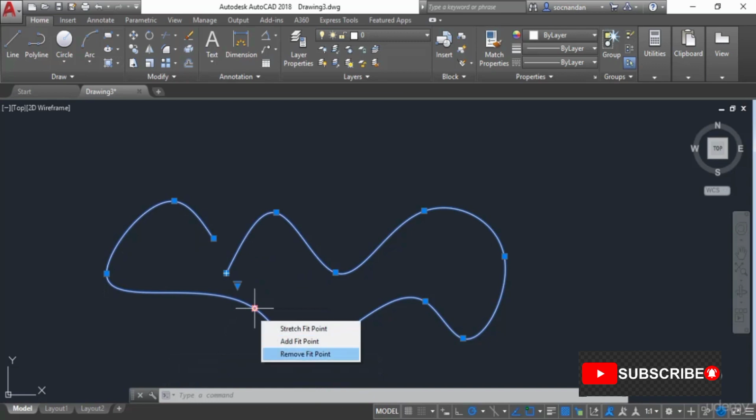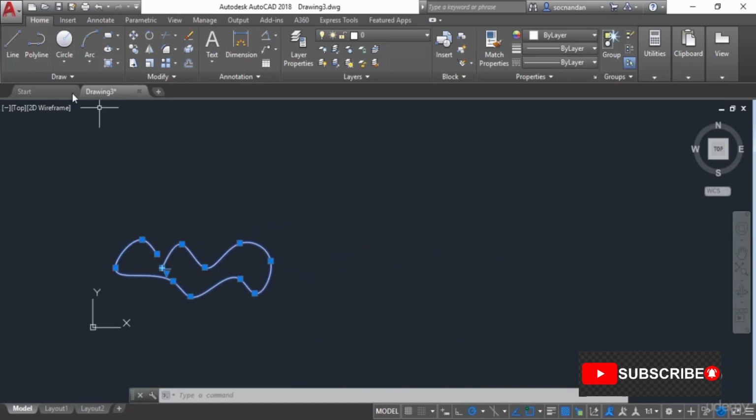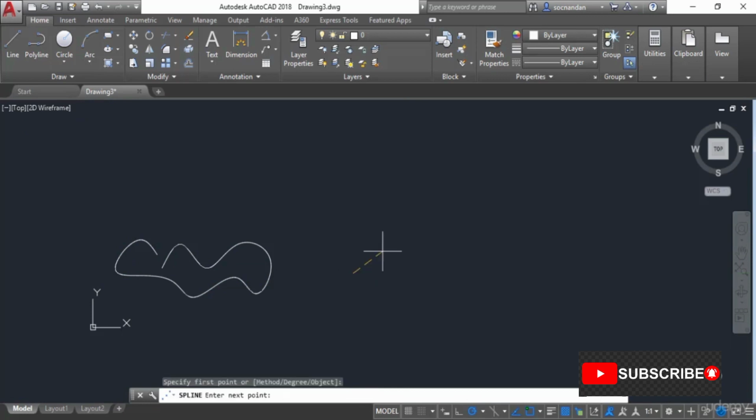So at every point where we clicked, we'll have this grip on the spline. Now let's make another spline with spline control vertices. So let's select this flyout and select the second option, which is the spline CV or spline with control vertices. Now in this case, I'll again click at a point and I'll make the spline. But in this case, if you look closely, you'll find that the spline is made in a slightly different way.